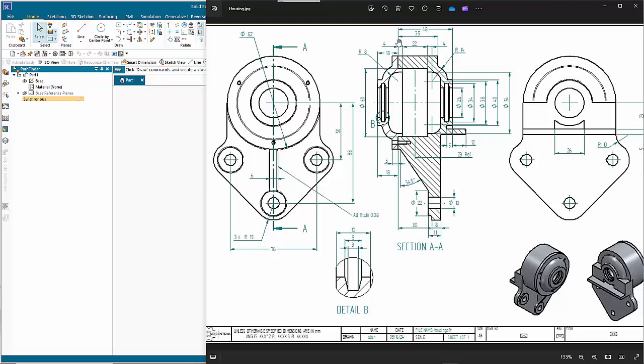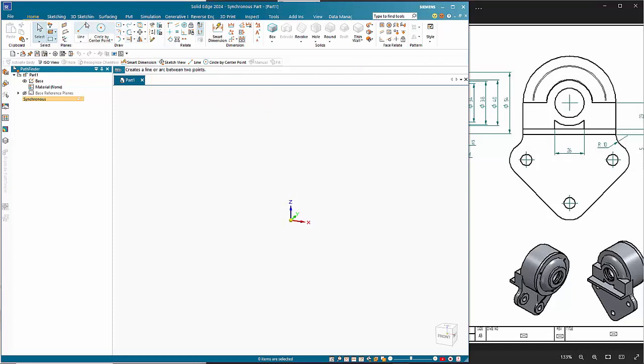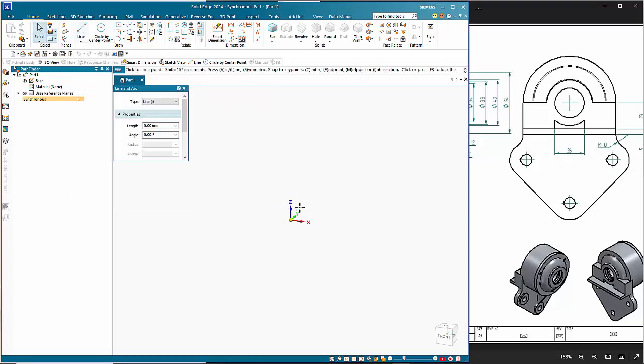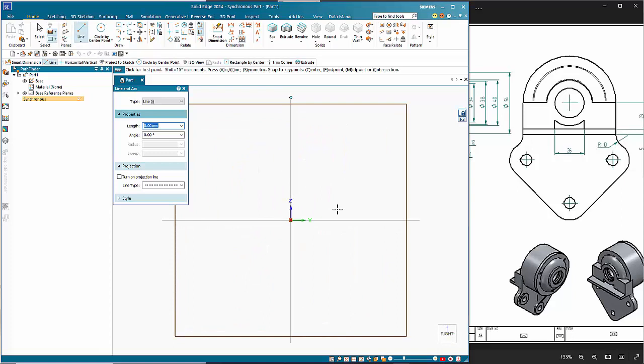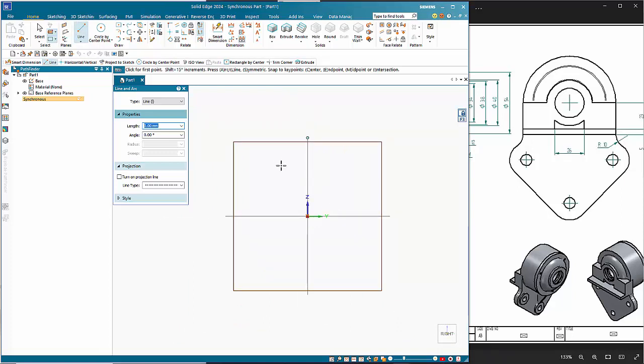So this is 35 wide, and we're coming sort of halfway across here, so it's 15 off from the left hand side, and it's got a diameter of 82. So I will start by creating a line and hover over the plane here. Control H takes me through to the sketch view, and then I can just draw my line in here and use a distance between dimension,